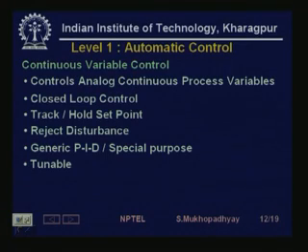Now because they are generic, they have to be tuned for a specific plant. So, you have to set controller gains for that specific plant, and that is called tuning. So, these controllers are tunable and they require tuning from time to time, and they are implemented typically on digital real time systems, like basically a processor system with an interface with the sensors and with an interface to the actuators.